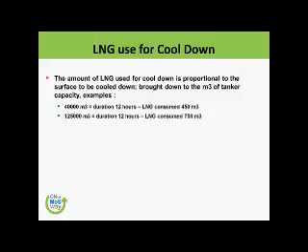125,000 cubic meter, 12-hour duration, 700 cubic meters. So we need a certain amount of liquid which we can consume, which we can calculate. But we can also do it when we are cooling down. We cool down one tank, we pass it to the second tank, we cool down the third tank, fourth tank, and then the hot vapor we can give. So now we are gradually cooling down.